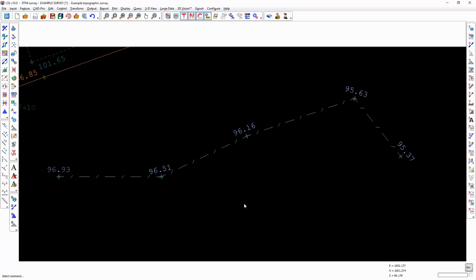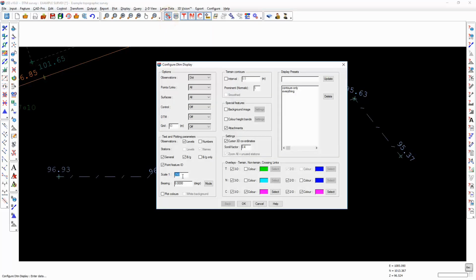for the current survey, and you will see that the level text is oriented to the feature to which it is attached. When we define level text, we define it as centimeters on a final piece of paper when plotting or exporting. Therefore, it's quite important to make sure that if you are going to be plotting this survey and you're going to be editing the levels text, that you make sure that you are viewing it at the scale that you are likely to be plotting it.